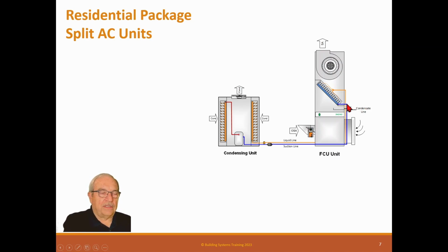and then we have a condensate drain just like the others, and we have a refrigerant circuit where the suction vapor comes back to the compressor, is pumped up, and the hot gas goes to the condenser coil, which turns it into a liquid. The liquid goes back to the expansion device, expands, and the cool gas cools the unit. Standard unit.